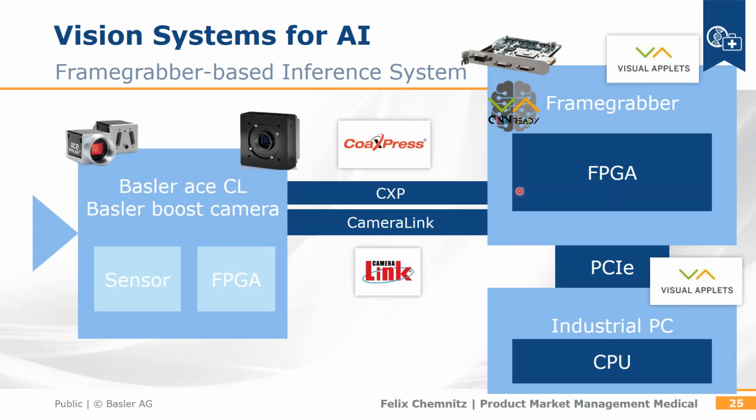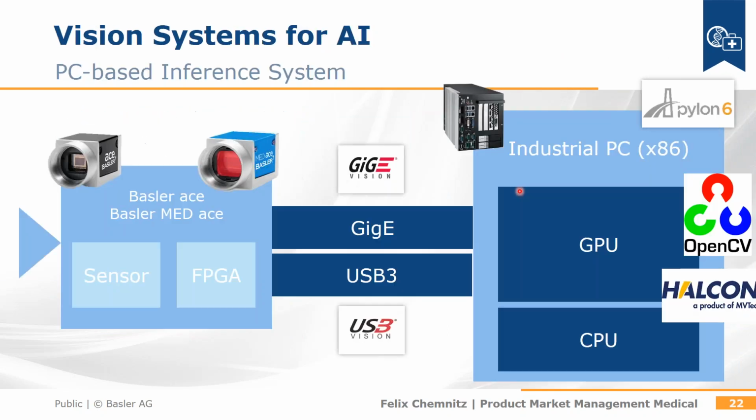The FPGA in the camera is kind of the brain of the camera, let's say like that. We put all of our firmware inside this FPGA. And yes, you can directly address this from Pylon 6 or, for example, the Pylon Viewer, which gives you the ability to grab an image, and you can influence each and every part of the firmware features, so set the exposure time, set the gain, and all of that stuff directly from Pylon. You can do this from the Pylon Viewer, or if you want, you can address this from your code directly.